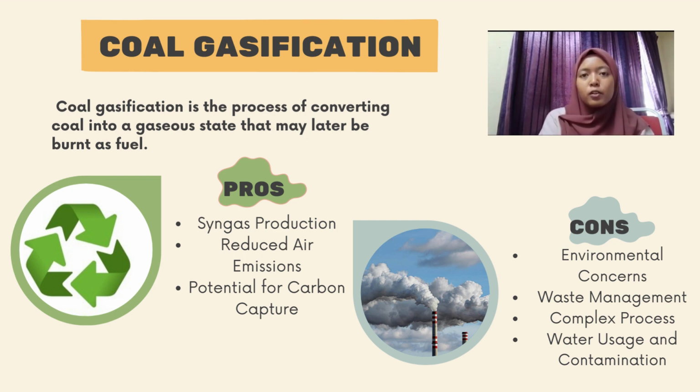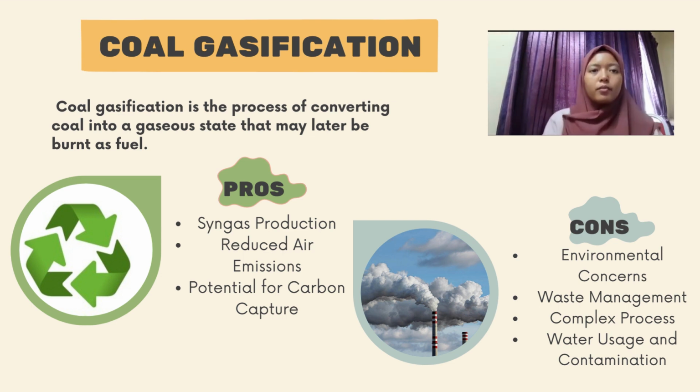Co-gasification produces solid waste in the form of slag or ash, which requires proper disposal. Depending on the composition and toxicity of the waste, it may pose challenges in terms of storage, treatment, and utilization. Moreover, co-gasification is a complex process. Maintaining the reliability and efficiency of gasification plants can be challenging, and unexpected operational issues may arise.